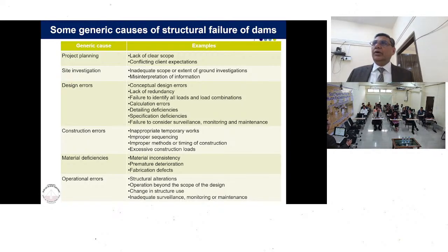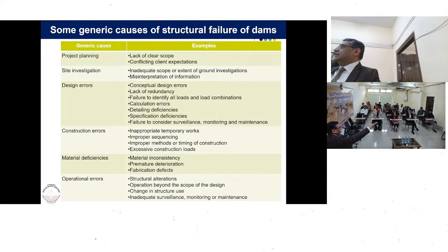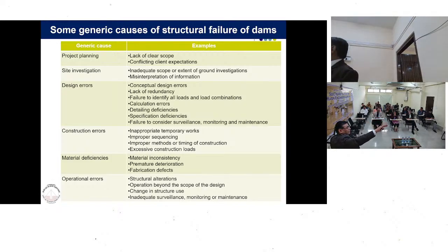So what they did was, at that particular project, there was a hill which was something like this. Okay, the hill slope, I am talking of a section: you have a top, then a near vertical fall, and then the hill goes like this. The surveyman took a point here and a point here and gave it for generation of contours.